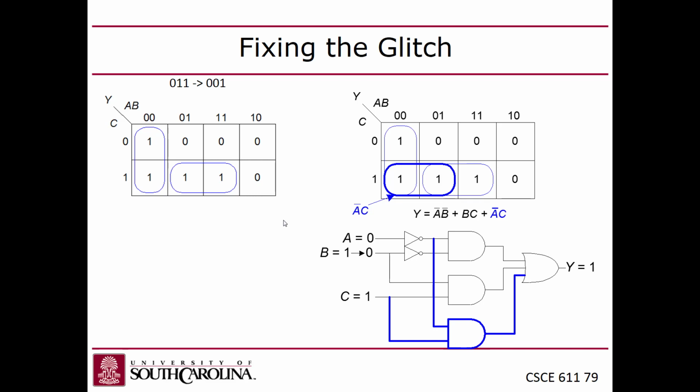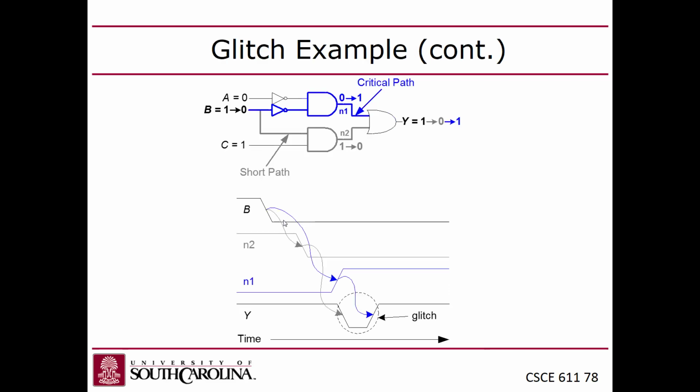So in other words, this circuit, now this is, I think, a kind of contrived case because it just so happens that this circuit happens to be in a sum of products form, right? Which is coincidence. So I think it's a little contrived. It's got these inverters, which just represent the complemented inputs, right? So we can analyze this circuit on a Karnaugh map because it's sum of products. If you do that, it's essentially just two implicants, these two guys, right? These represent the two inputs into the OR gate, these two groupings.